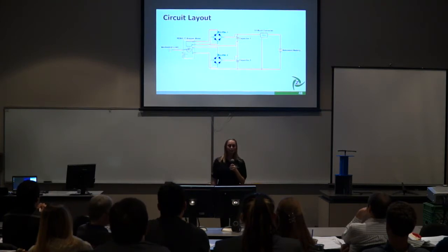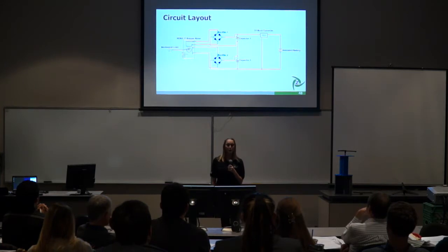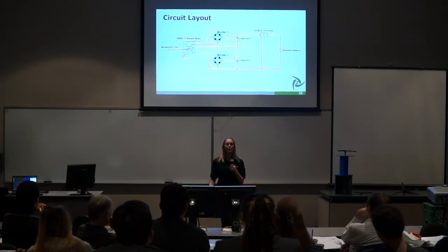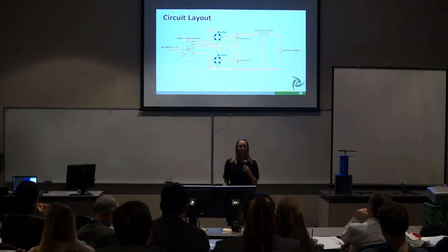These capacitors further smooth out noise and fully ensure a DC signal, and additionally the signals are combined at that point. The signal is run through a 5-volt buck converter. This is a voltage regulator, meaning that there'll always be a 5-volt output from that point, as long as there's a 6 to 30 volt input, which Project Zephyr believes will be sufficient.